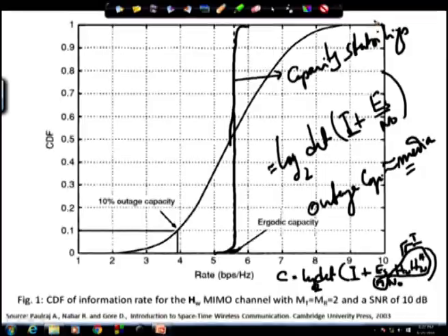All we are saying is that if we have a very large number of antenna elements at the transmitter and the receiver side, and the links are spatially white, that means they are orthogonal, what we can achieve is almost a stable link which does not vary. So we are almost able to provide the capacity of an additive white Gaussian noise channel. That is very important, and in fact it is M times the capacity of an additive white Gaussian noise channel. So it stabilizes, the link is not fluctuating anymore.